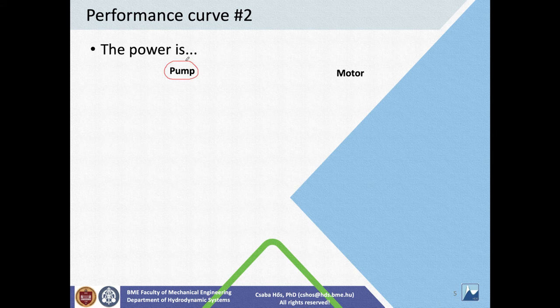You're rotating the shaft, for example, with an electric motor, and your pump will deliver flow rate and pressure difference, so you will get hydraulic power. But if you think of a gear pump, you could use it the other way around. You use another pump to push liquid through the machine. So you force a flow rate through your gear pump, and it will rotate, and you can use it as a motor.